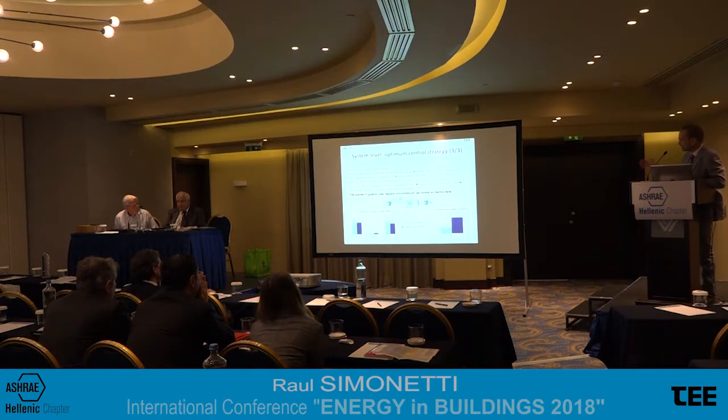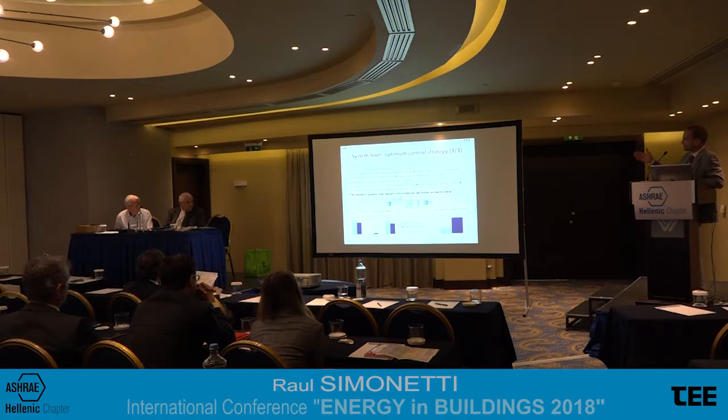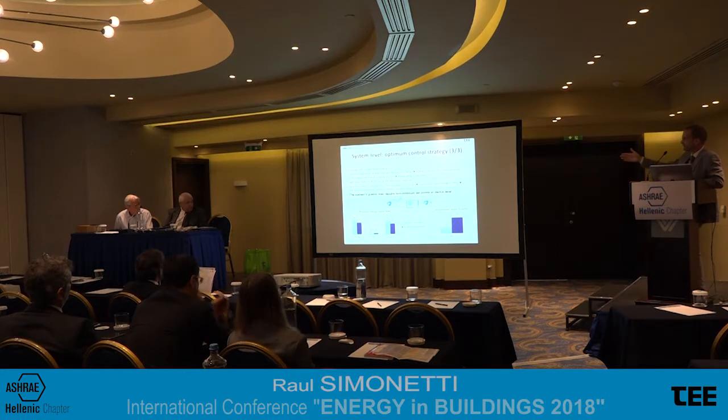And this is quite interesting. I'm going to show you now two cases. This is a case of a ventilation system, a very simple one. This is an extreme case just to explain to you the meaning of controlling a system in this particular way. This is a ventilation unit with just a cooling coil doing cooling by a chiller and an evaporative cooler, DEC, spraying water. When water evaporates in the air, it does cooling and also humidification at the same time.